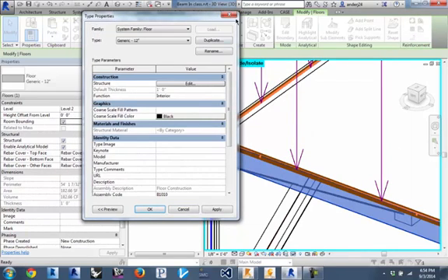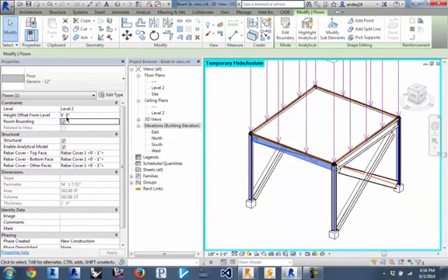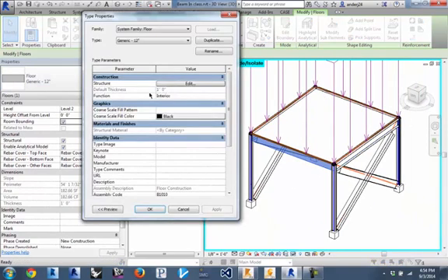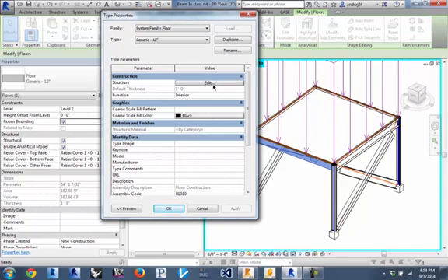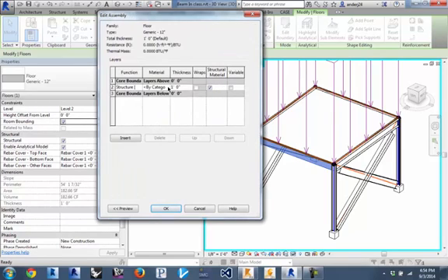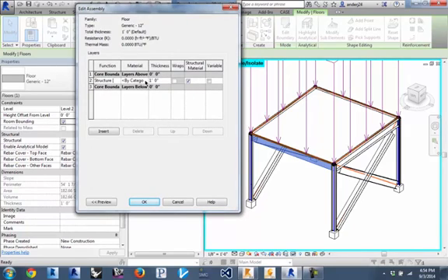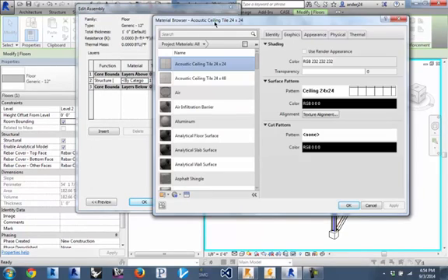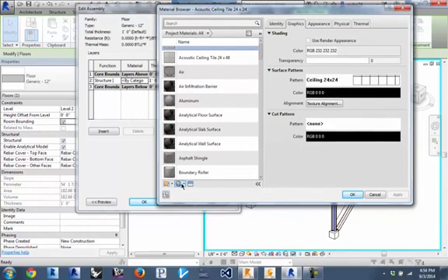So you could set up your own generic floors and then change the material properties so that it has a different loading characteristic, so you can understand what different assemblies might be, right? So you might be able to estimate the 5-inch concrete with a raised floor system with carpet or with tile, and get an idea about how much that weighs and throw it in there. As a generic slab, just changing that number from 110 pounds per cubic foot, I would guess that with all the air in the raised floor, it might be something like 40 pounds per cubic foot.